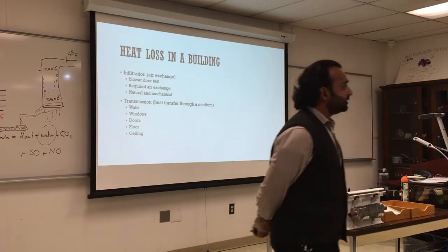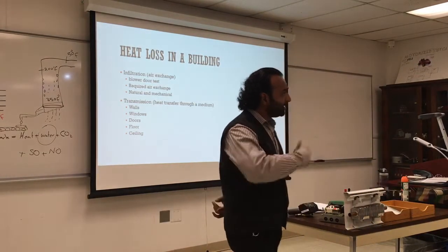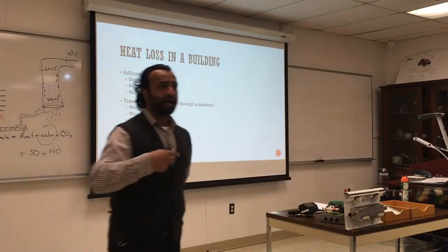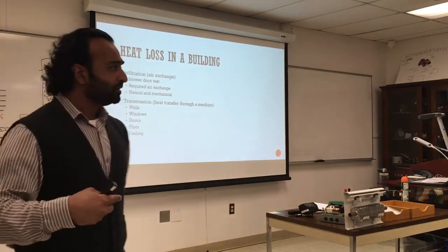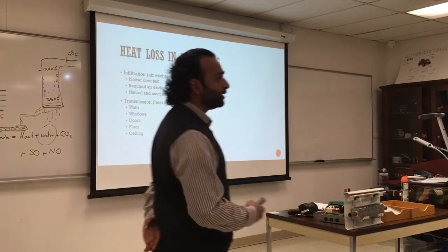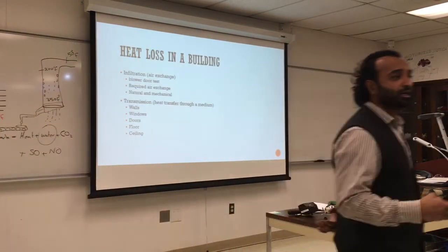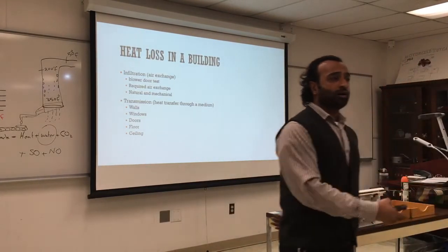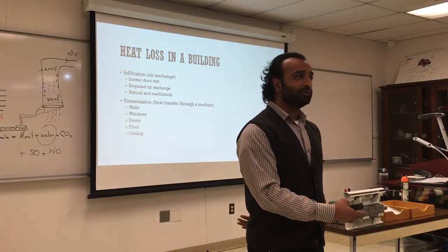It pushes the water around. It adds pressure to the water. It has an impeller in it. The impeller keeps pushing the water forward and it adds pressure to it. When you have pressurized water, it will move. And also with water, there is displacement. You cannot push water if you don't have something pulled in, right? That's why a lot of pumps need priming. If there is no water in the pipe, the pump is not going to work.